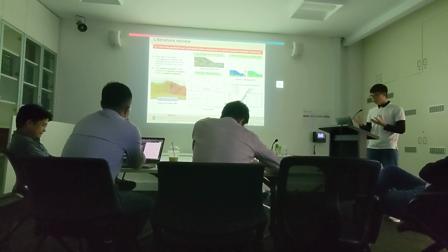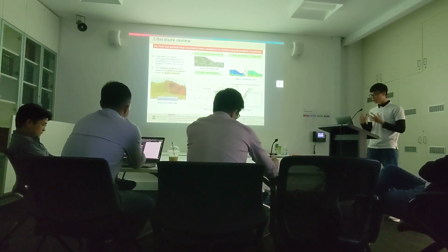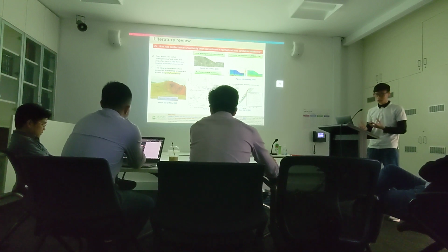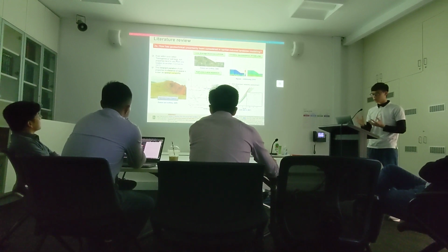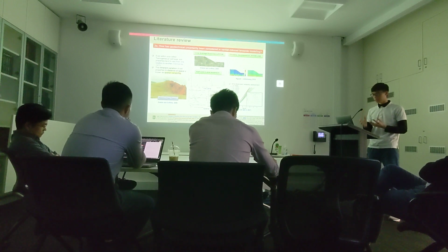The slope profile of a natural slope is unlikely to be completely uniform due to the complex deposition and alteration process. So even with a so-called homogeneous soil layer, soil properties tend to vary from one location to another, and we call it spatial variability.